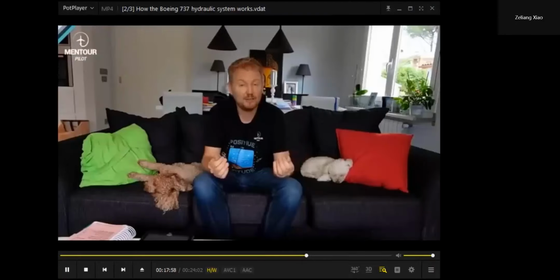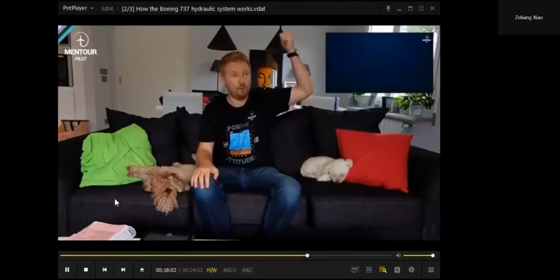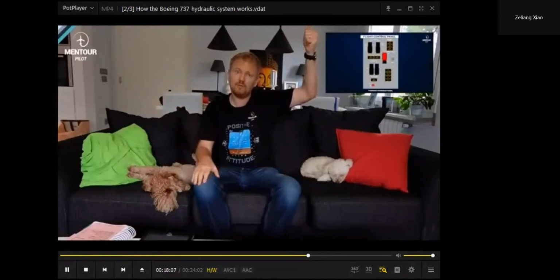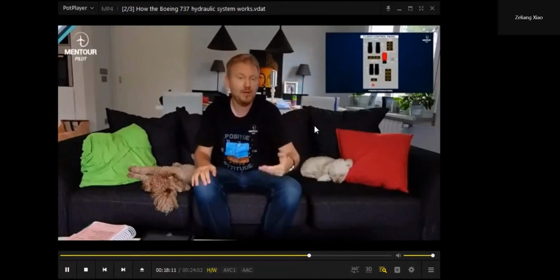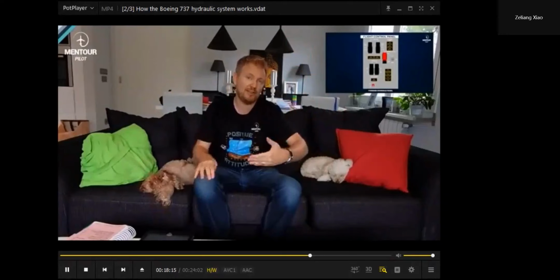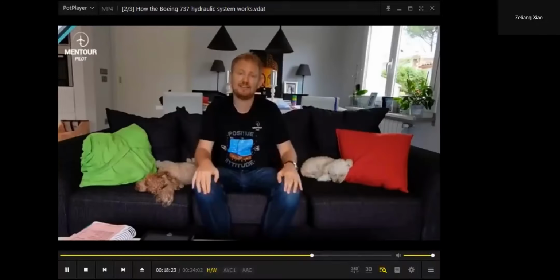And the trailing edges, you'll have to drive them out using an electric motor, which you'll actually have to hold down to make sure that the trailing edges come out, and you basically just let it go when you have the trailing edge you want. And as the trailing edges come out, the leading edges will be automatically extended depending on what flaps you're using, but you will not be able to retract them. Right? The standby system is only extending the leading edges, it will not retract them.